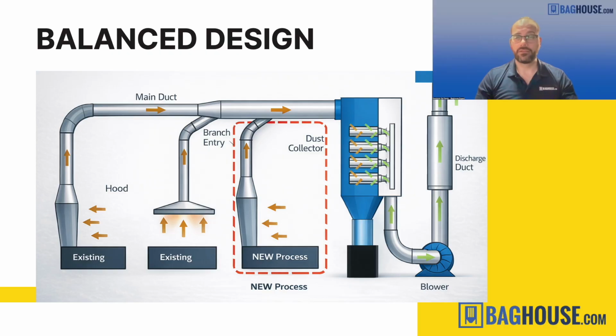So now the next subsequent duct, the trunk, where the 4 and the 6 come together, we have to add the total volume of both of them together and then decide what is the proper size to make the trunk piece there going back. So a 4 and a 6 coming together might result in a 7, maybe an 8. And then we have a third pickup now that joins. And there it needs to resize up again.